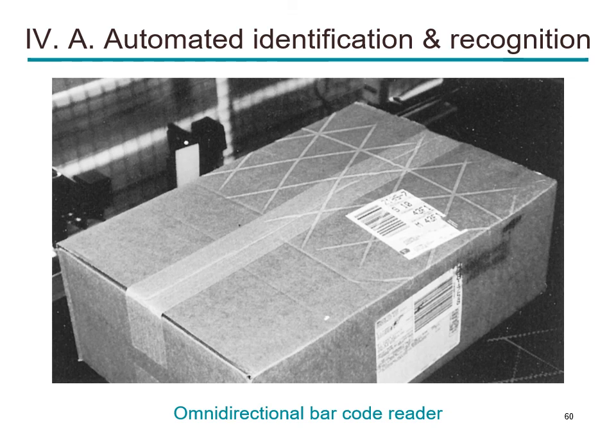Usually, the initial versions of these barcode readers are single directional. It means that it sends a laser beam, and this beam should be vertical to the barcodes in order to read it. But in that case, you need to arrange the orientation of the part to be able to read, and sometimes it's difficult to do this if the part is especially heavy, or if you want to read the barcode on a conveyor, so it creates problems. And in the new technology, we have omnidirectional barcode readers, so it sends the laser beams in this form so that whatever the orientation is, it's possible to read the barcode information.